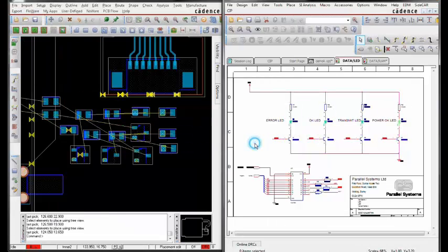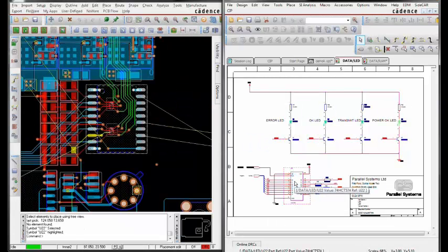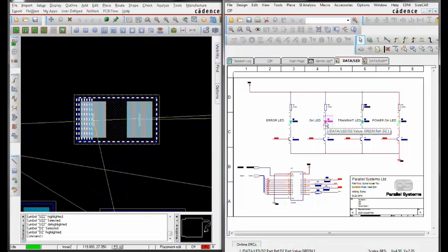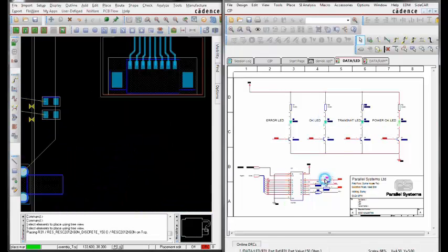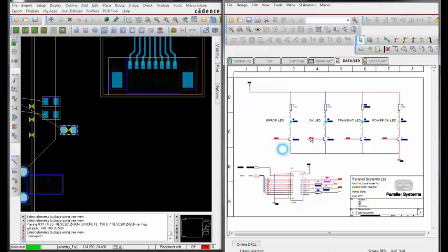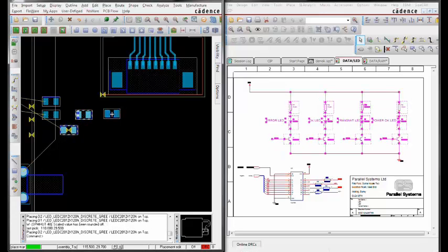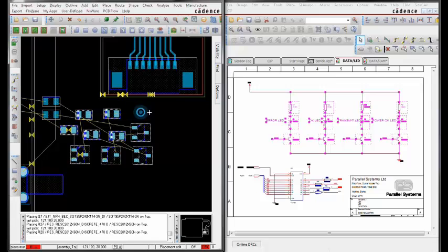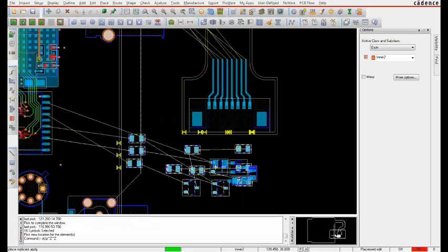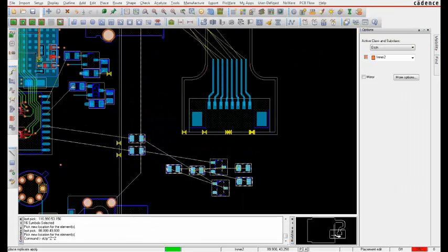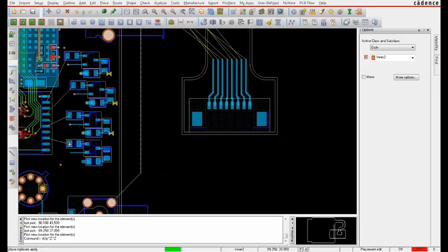in seconds. Cross Probe allows you to select a component in the schematic and have it zoom to its location in PCB Editor. Users can lasso a section of logic and the components are ready to place in order on the PCB. Design reuse lets you use existing design IP inside the current design or across multiple designs.